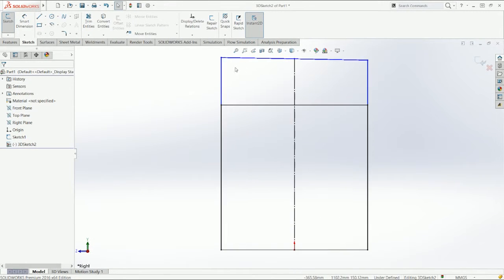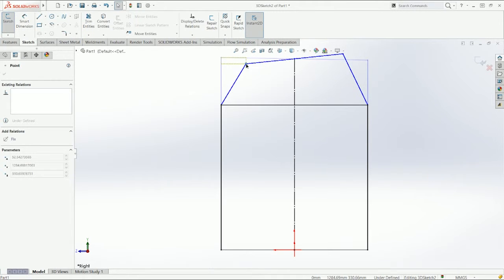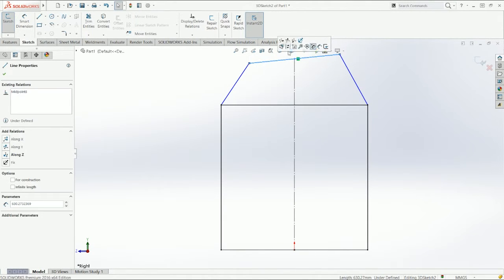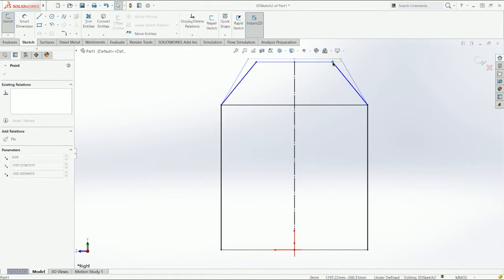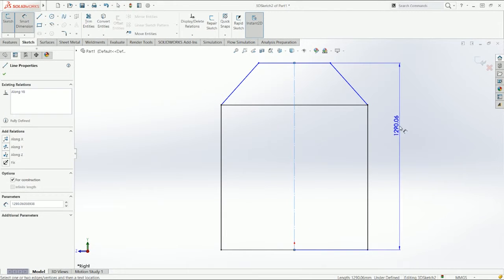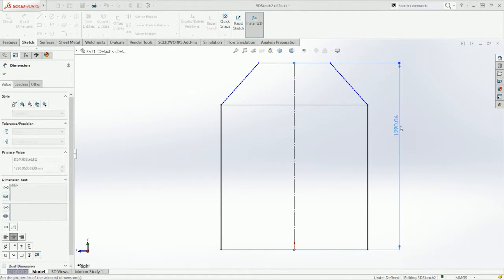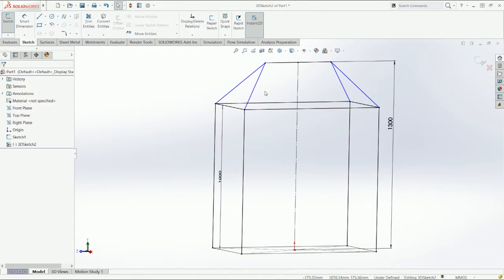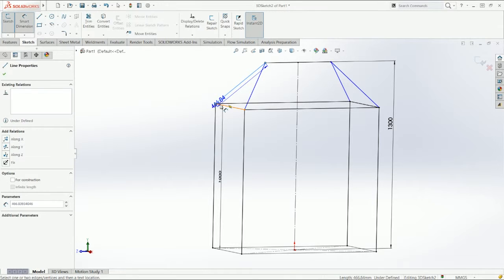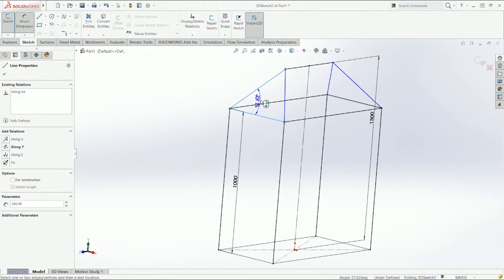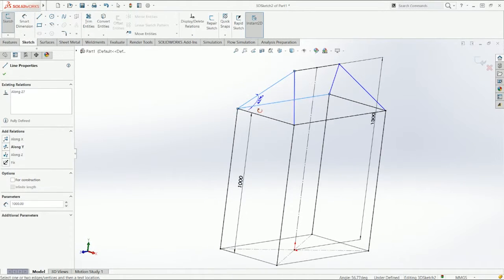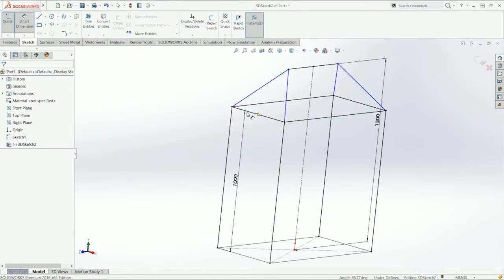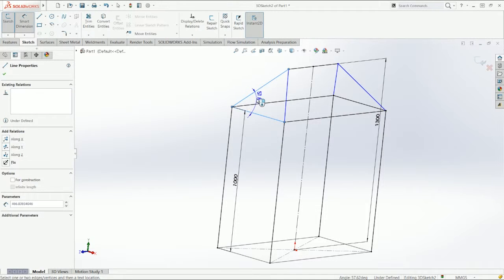And if you look at it from the side, if you draw this, you see how the lines automatically update. So I'm just going to say this one goes in the Z direction, so they are always at the same height, and just define this line to be 1300 mil. Just to finish this, I'm going to say from there to there. You can define an angle there, or just click on the other line so you can get another angle. So let's just say we want 45 degrees.